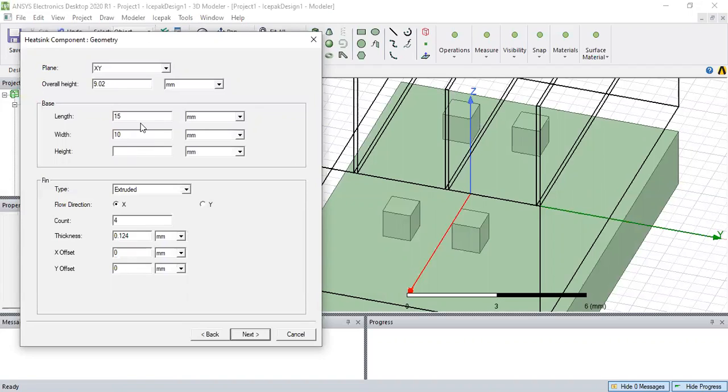Relatively, the base is not that thick. It can be around, I would say, 10%. No, even less than 10%, probably around 5% of the height. You can check with other heat sinks you look up online. They will include some of their dimensions.